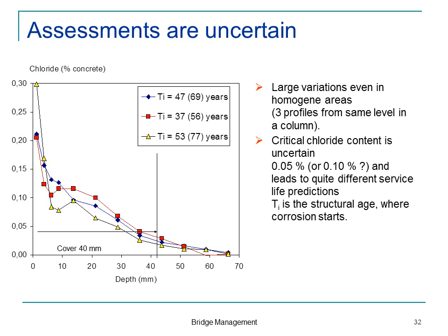And then we take three cores, right beside each other on a concrete wall which faced the highway, taking about this distance from the ground, this distance between the cores. And you might say, oh, that looks somewhat the same. Yeah, reinforcement is in here. If I should make a prediction of when corrosion would start, then that prediction could range from corrosion starting when the bridge is 37 years old or when it's 53 years old. Normally, we don't take three cores, we take one.